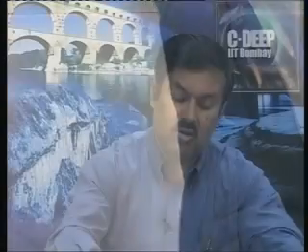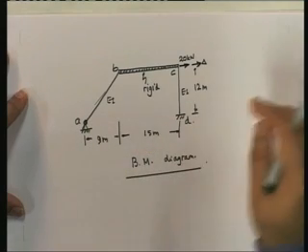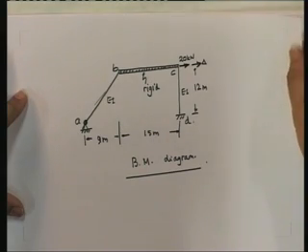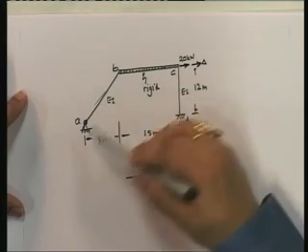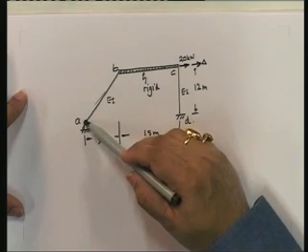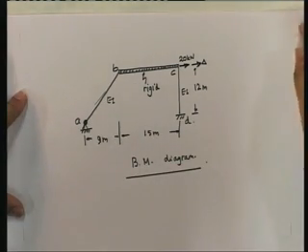Okay. So now the first thing is that let me write down the member force relationships. First, let me go through it in an algorithmic state, just like I had done for force method. What is the first step? Identify number of degrees of freedom and identify the degrees of freedom. If the degrees of freedom are related to a hinge, end hinge, then we can forget those degrees of freedom. Those are non-essential degrees of freedom. Okay, so although this is a 2 degree of freedom structure, this is a non-essential degree of freedom because the moment at this point is equal to 0. So we have only one essential degree of freedom. So this is a single degree of freedom structure.